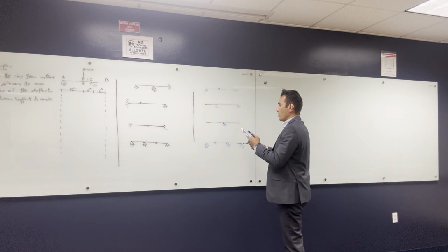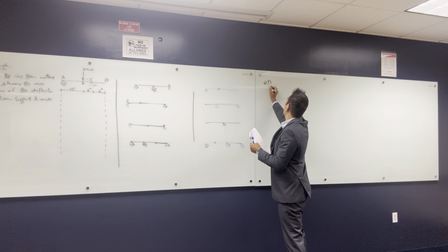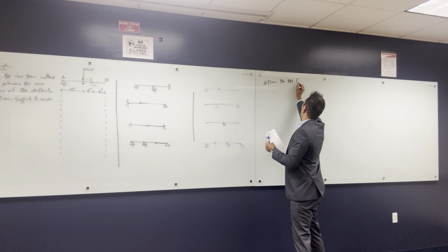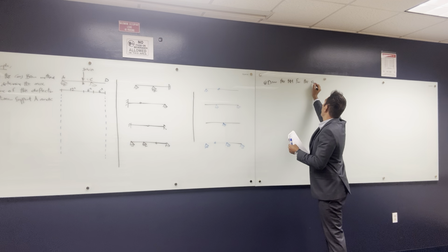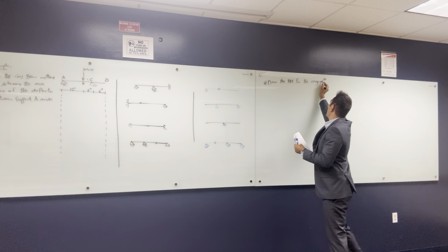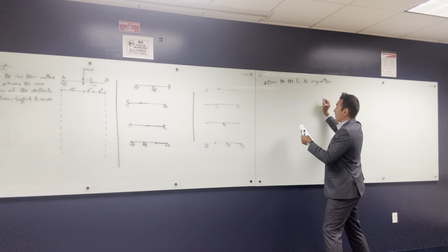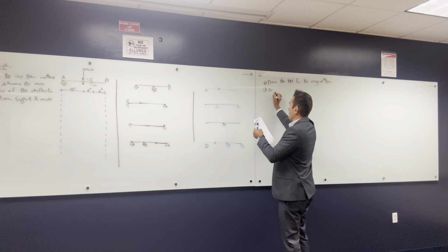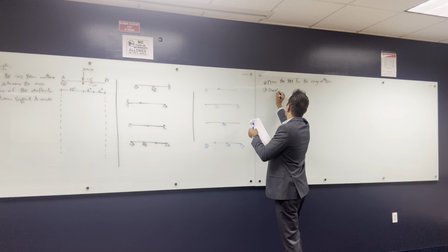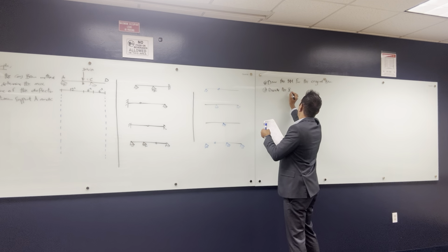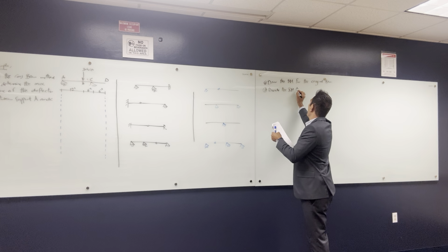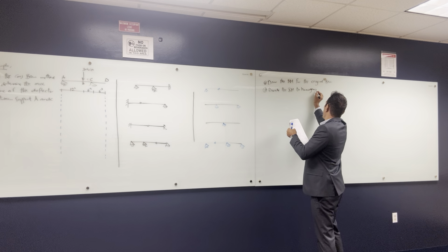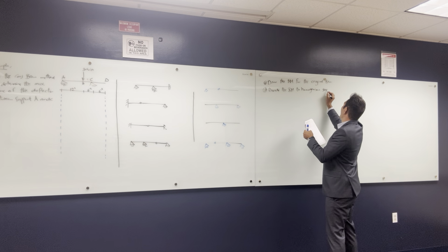Number one, draw the bending moment diagram for the original beam. Number two, divide the bending moment diagram into homogeneous segments.